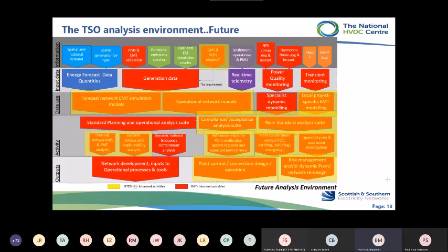And onshore, the levels of inherent synchronous machine behavior are again reducing as greater contributions from converters arise. And what that means is no longer are you in an environment where you can fit your framework around inherent behaviors. You need to fit your framework of analysis around the modeled performance of control systems. You need to be comfortable that across a range of operational scenarios, those control systems combine and complement one another, and where they don't, damping solutions need to be defined.